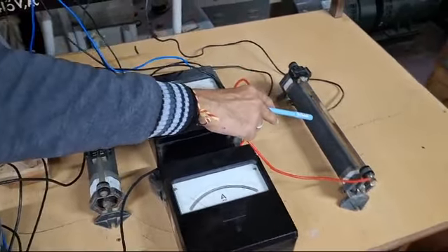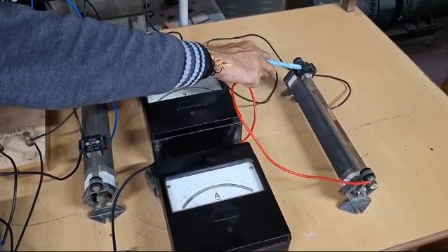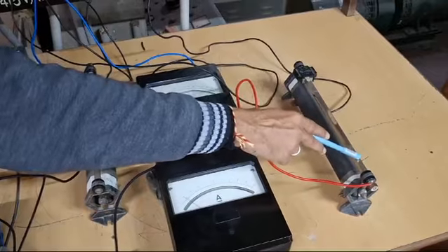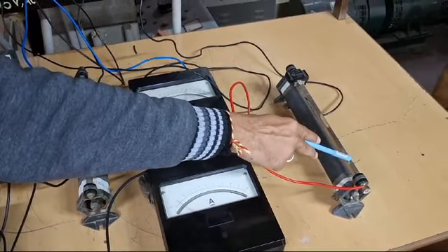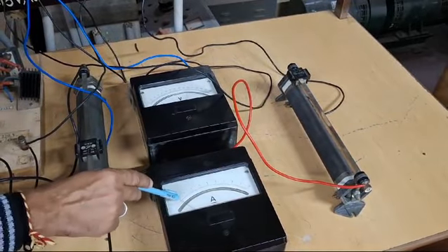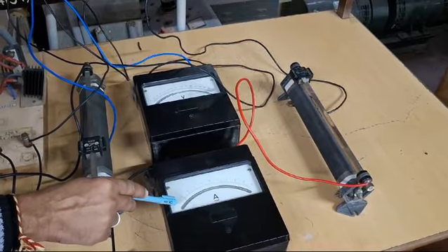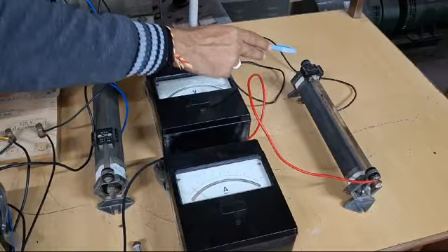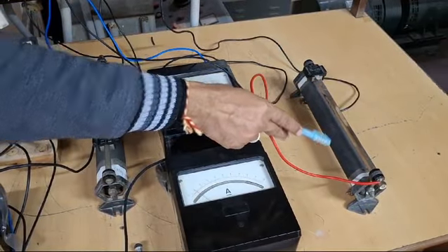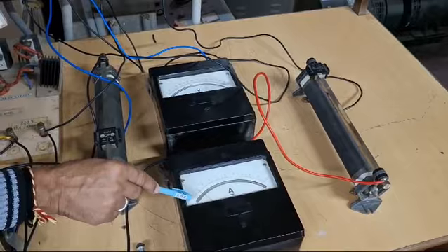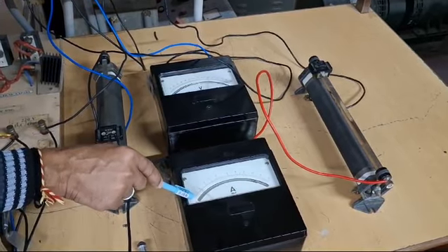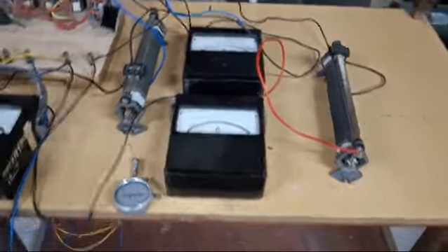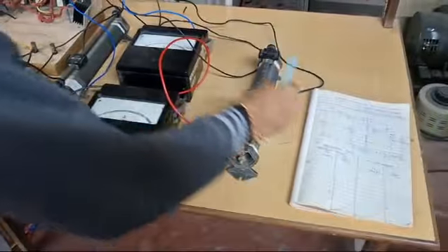Right now the field winding rheostat is set to 0, and I will increase its resistance step by step. So the field current If is going to reduce, and as the field current reduces, the flux phi will reduce and our speed will increase. So periodically we are going to increase the resistance by means of this rheostat, decrease the field current and increase the speed. These are the readings we are going to take now. First step, you can see that the rheostat has been set to 0.